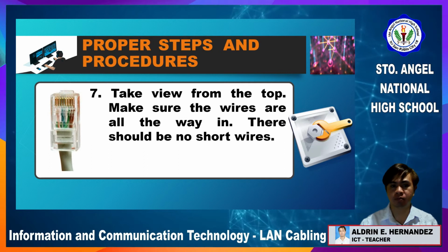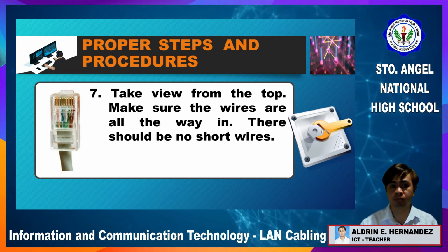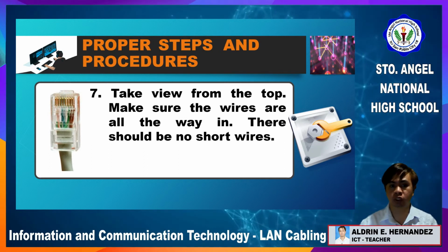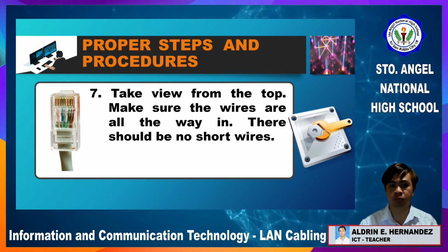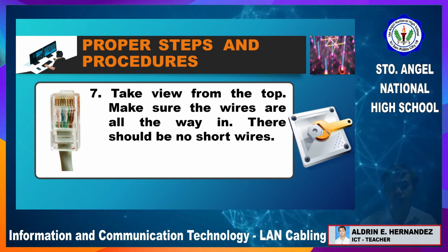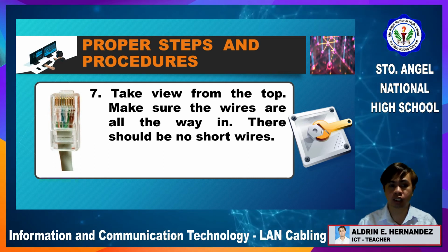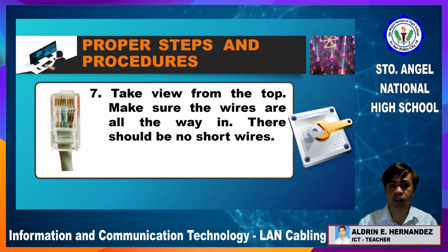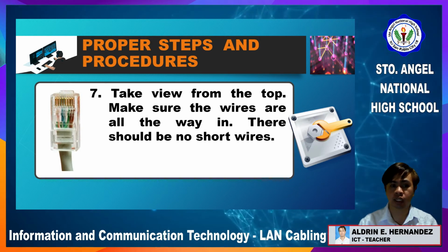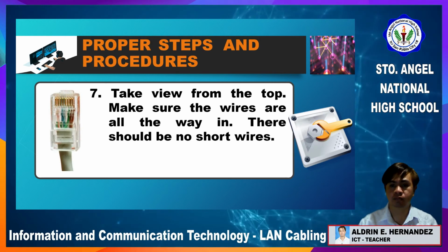Step number 7. Take a view from the top. Make sure that the wires are all the way in. There should be no short wires. Class, we need to see if we connected it right, checking if the strands of wires are connected right to each pin.